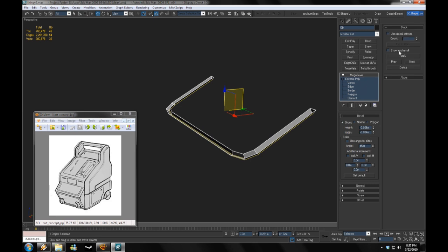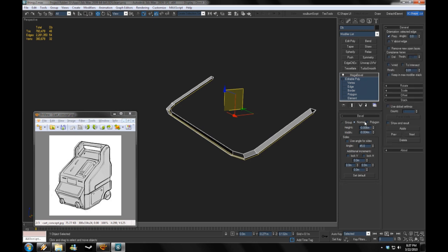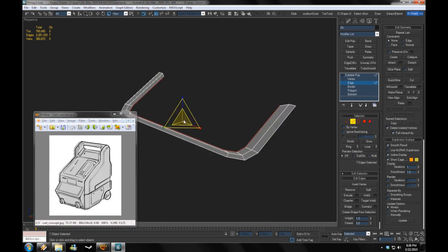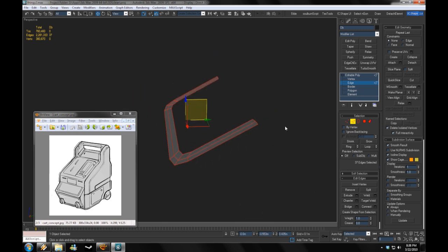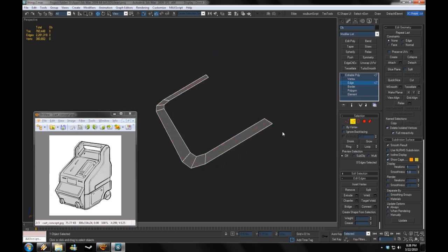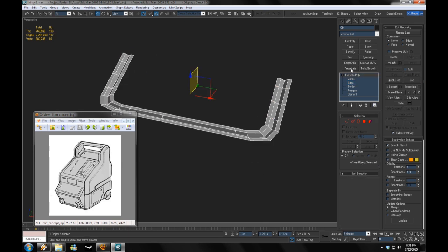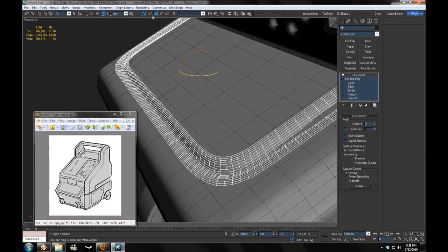You know, it didn't really work that well. I'm just going to manually end up doing it by selecting parts of this, scaling it in, moving it how it sees fit. And also I used Make Planar there to make sure that it is all on the same angle. That's another tool that's very useful.